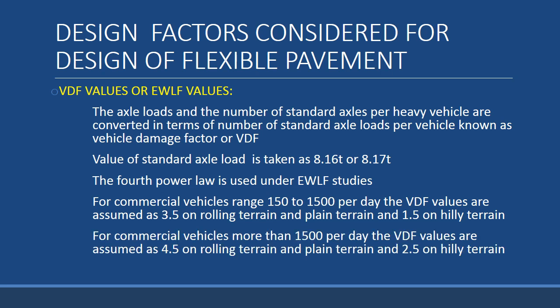Next, for commercial vehicles of more than 1500 per day, the vehicle damage factor values are assumed as 4.5 on rolling and plain terrain, and 2.5 on hilly terrain.